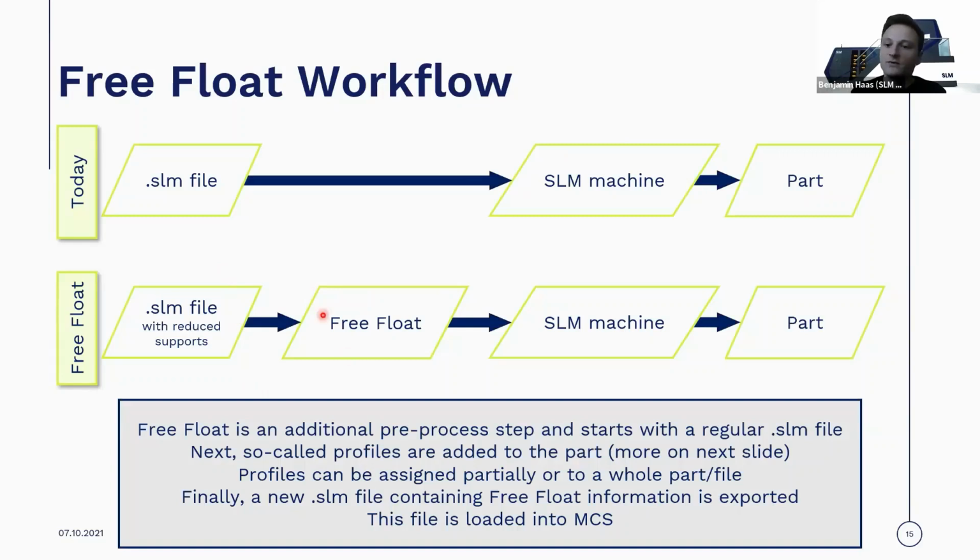So that's the FreeFloat desktop software, and the actual goal of that software is really to assign those profiles to the parts where they're actually needed. And then in the end, this creates another SLM file. This goes onto the machine, and then in the end, you have the part at your hand.